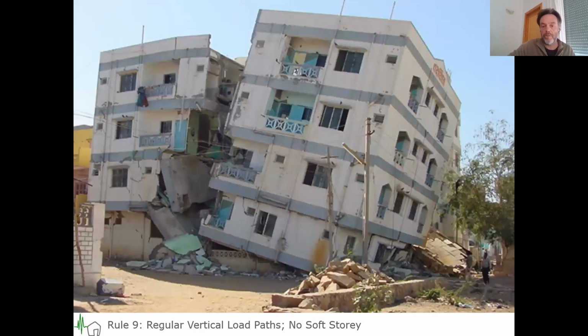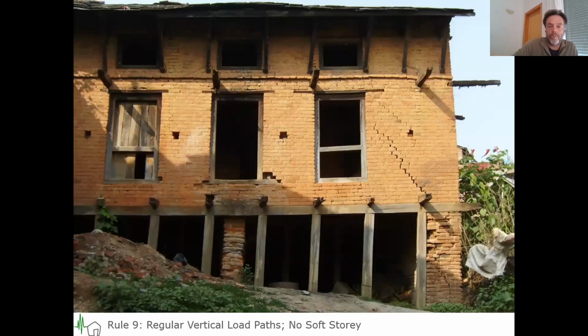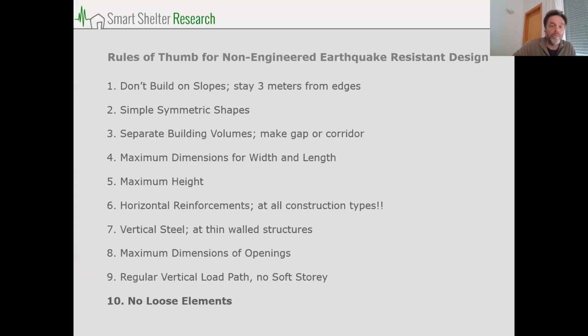And this is a picture from India. But those ground floors, if they have no structural resistance, they literally get slammed out, and buildings will fall on top of this. In Nepal, what we saw a lot is a heavy block of masonry standing on, let's say, a layer of wood pillars, and you can already see. This picture was taken before the earthquake, but this building is tilting in this direction, and you see this shear crack already developing here. I doubt that this has survived the earthquake in 2015.